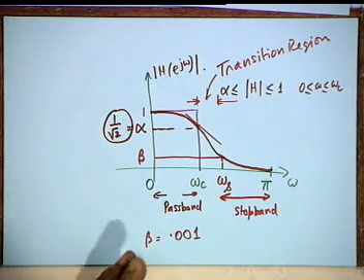So, a filter in practice, digital or analog, it does not matter, shall have a pass band, shall have a transition band, and shall have a stop band. What typically you shall be specified is the bandwidth of the pass band, the pass band tolerance. There is nothing sacred about 3 dB, it could be 1 dB. In a more sophisticated situation, it could be 0.1 dB, all right. Similarly, you shall be specified the stop band and the minimum attenuation in the stop band.